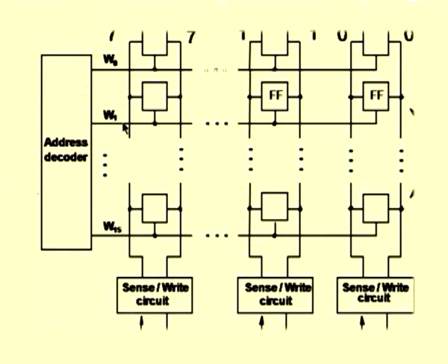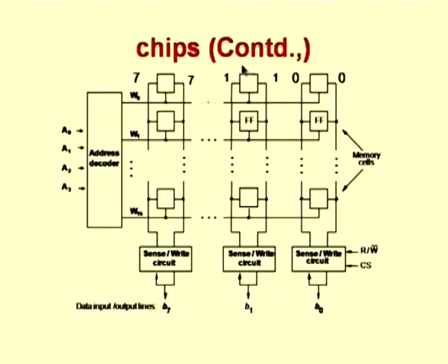So, this is how the read write will take place in any typical memory structure. Normally, whether it is static RAM or dynamic RAM, terms that we will discuss in detail later, whatever be the type of RAM, you will find that it is basically an array of cells, and you will have addresses specified and the data that is sent to it through the sense and read write circuitry. So, this is what you will have.